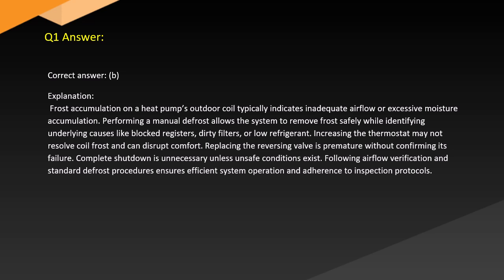Replacing the reversing valve is premature without confirming its failure. Complete shutdown is unnecessary unless unsafe conditions exist. Following airflow verification and standard defrost procedures ensures efficient system operation and adherence to inspection protocols.